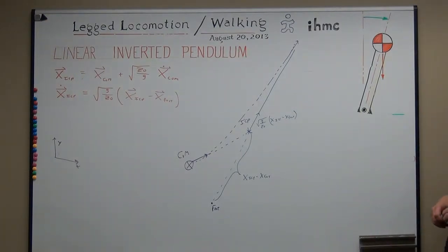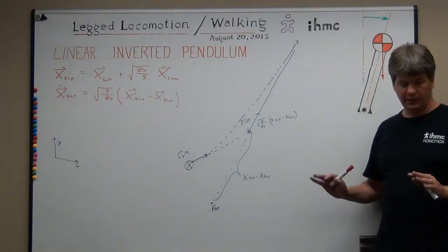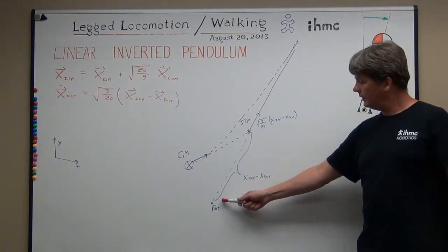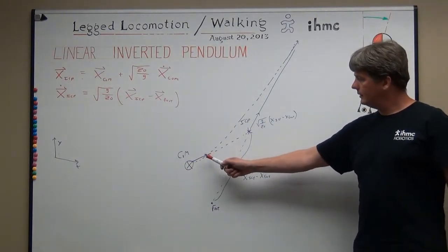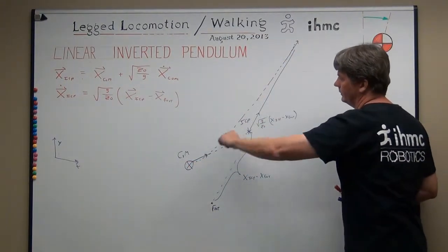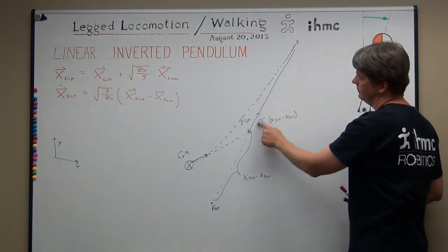So, just talking us through, from the placement of the foot. Your foot's here. Don't assume we're taking a step for this analysis. Right, the foot's here and will stay there. The center of mass started here, moving in this direction, but the velocity will change moment by moment? Yep. So the center of mass is going to take this path, whereas the instantaneous capture point is just going to take the straight line path.